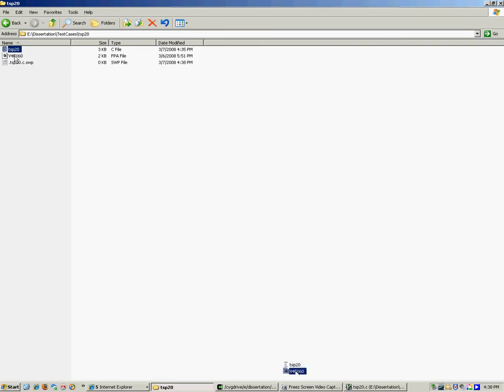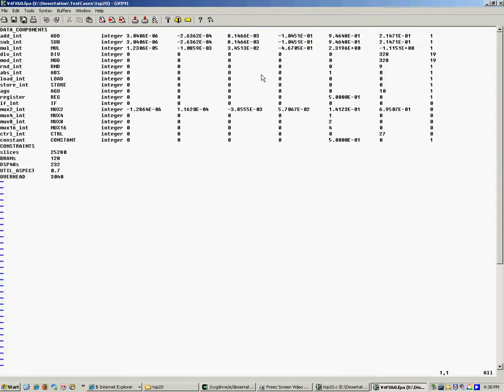The other file to look at is the constraints file. This is a constraints file for a Virtex 4 FX60 device, and a similar architecture description file could be generated for any FPGA. We've got a list of data components that the system can use as building blocks, also a set of constraints: slices, block RAMs, DSP48 units.